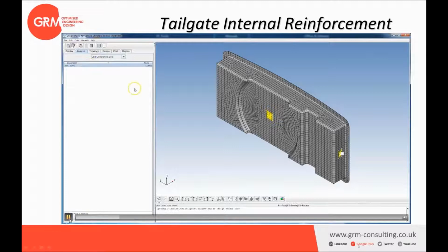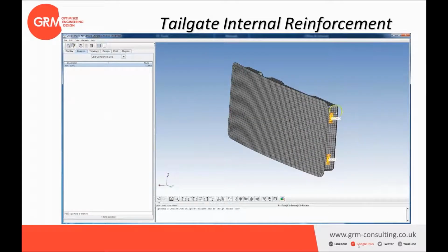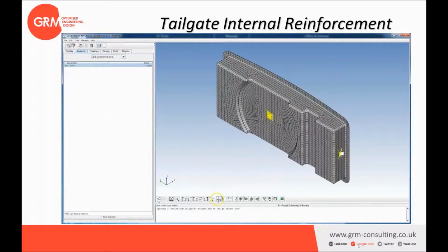So we have some constraints, obviously. Here on the right, the translation on the X and Z axis have been restrained, whereas on the left, the rotation on the vertical axis is allowed only. And 3 static load cases have been defined: the vertical, lateral, and fore-aft.